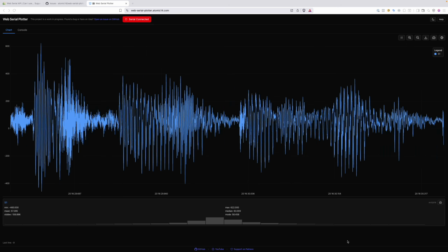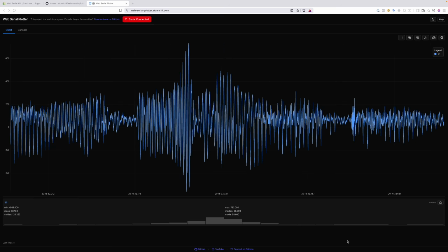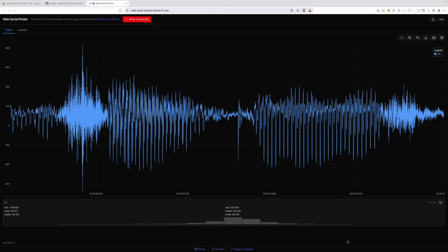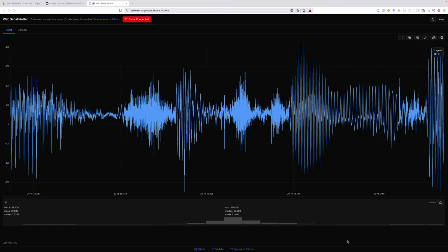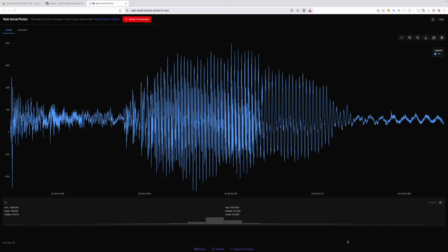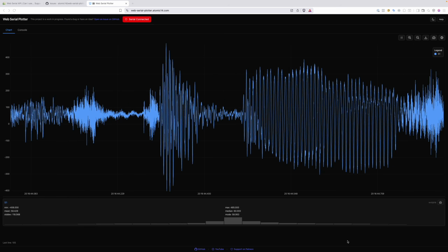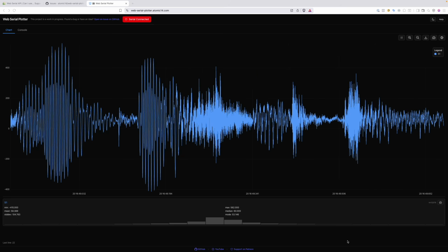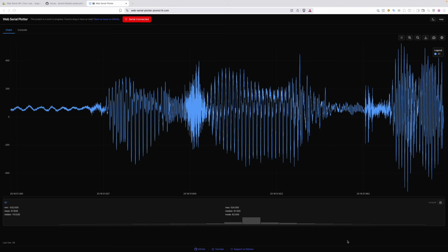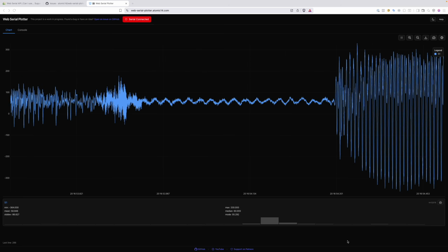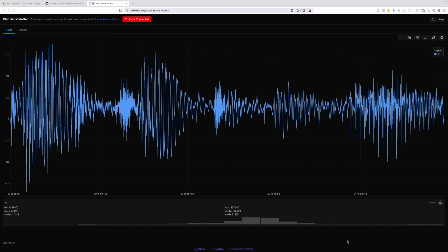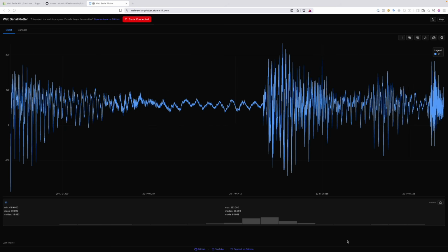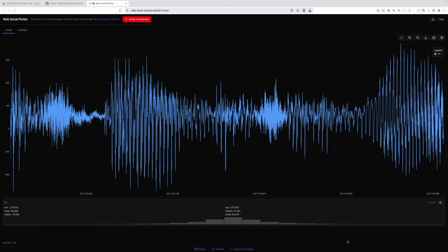So just thought I'd do another quick test. This is actually audio data. I've got my board hooked up with its microphone, outputting the samples. I'm doing this, I think, at 16 kilohertz, which still seems to work. I need to do some testing to see if it's dropping any samples, but at the moment, looks quite good. I'll see what I can actually push this to. Maybe I can go up to 48 kilohertz or something and still get good results. The USB serial connection does tend to be very fast, so it's really down to how performant is my code for actually doing the parsing and the drawing. So I'll do a bit more experiments on that and push the limits of this.